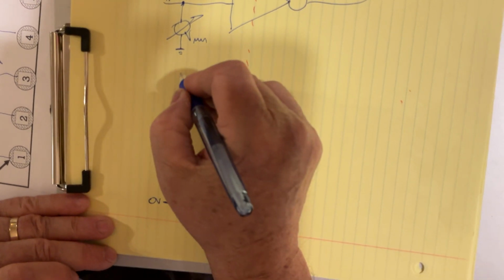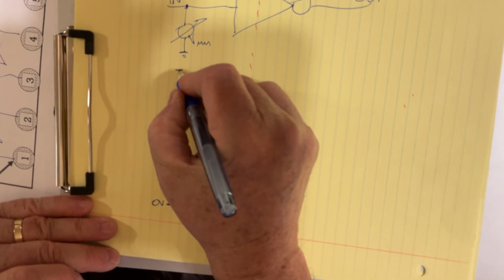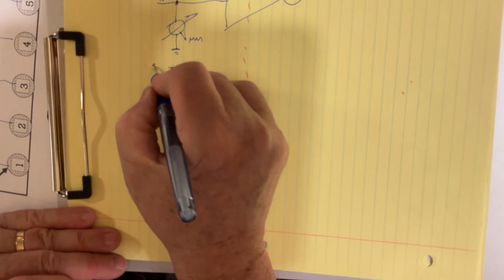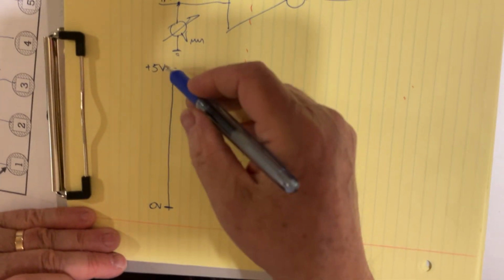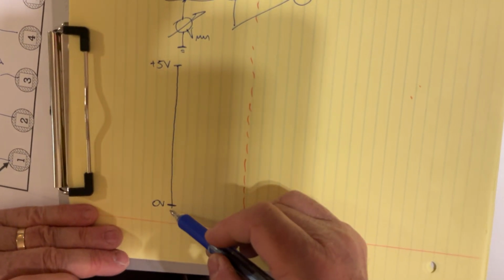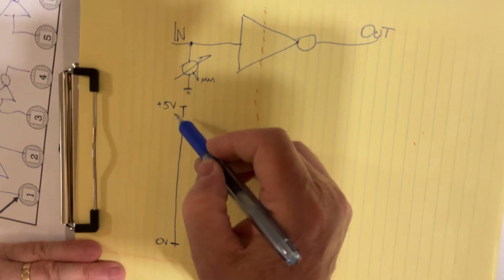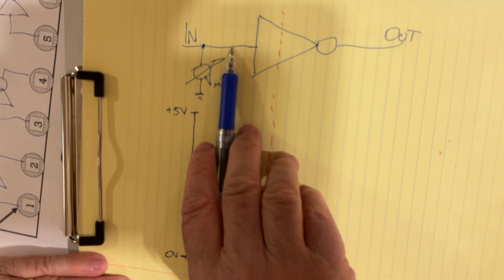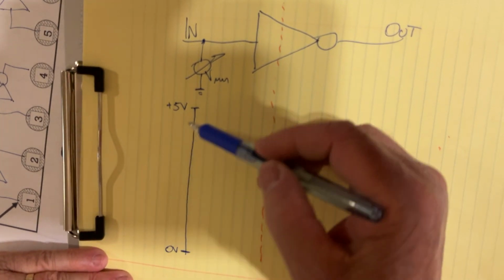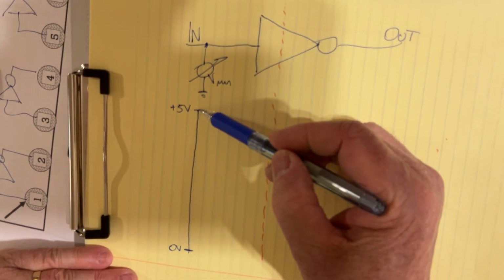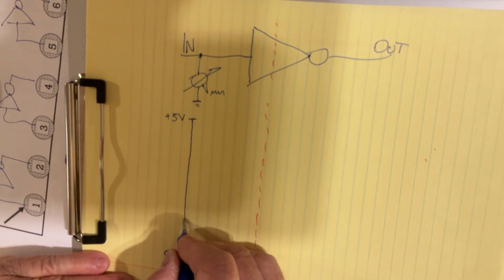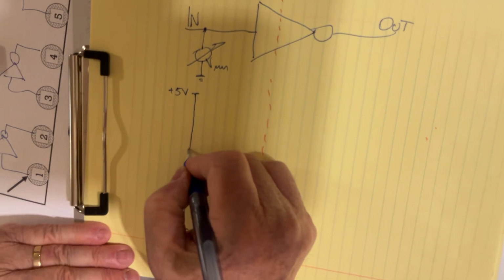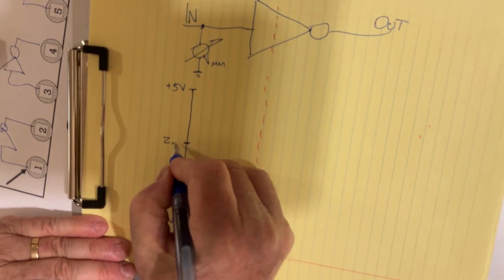And if you consider all this line up to here, that vertical line is going to represent the whole range of values between 0 and plus 5 volt. Simply because the values you measure with the voltmeter, either at the input or the output, cannot exceed the value of the power supply, which is 5 volt. Somewhere here is 0.8 volt. And somewhere here is 2.0 volt.